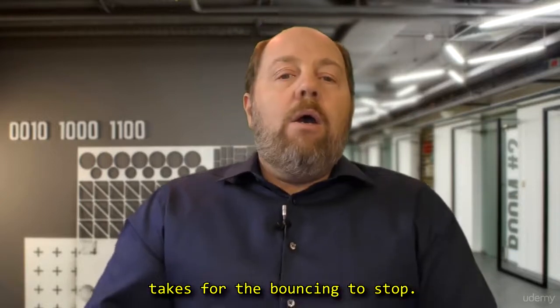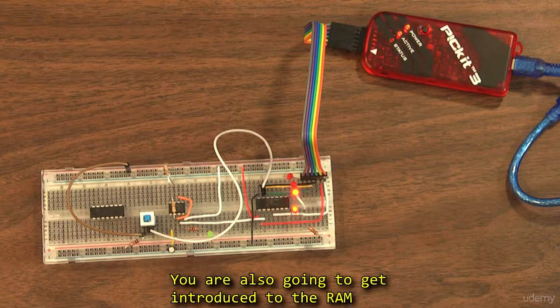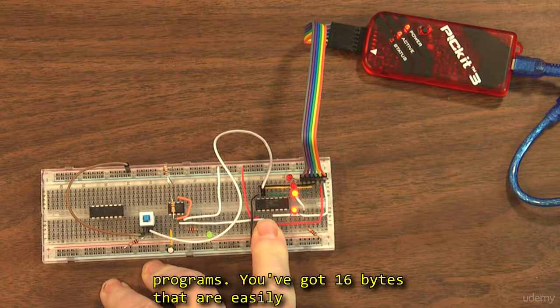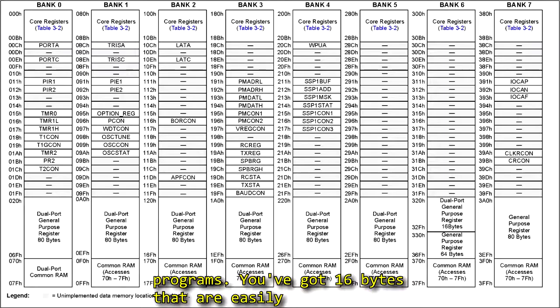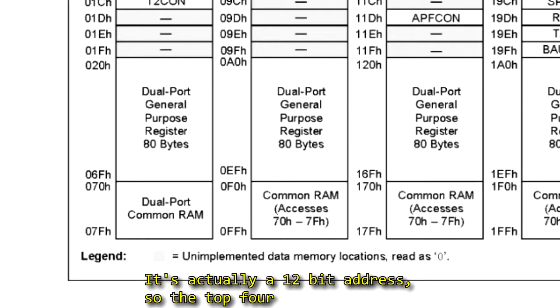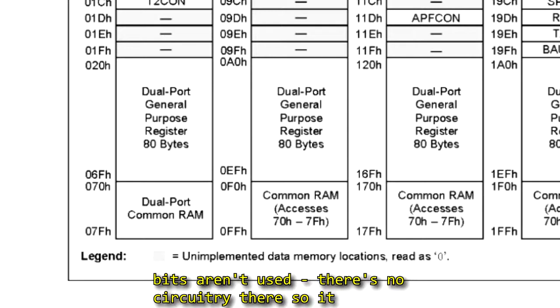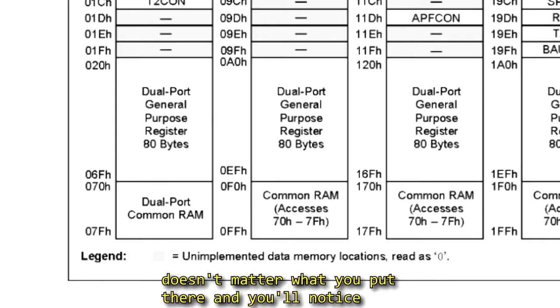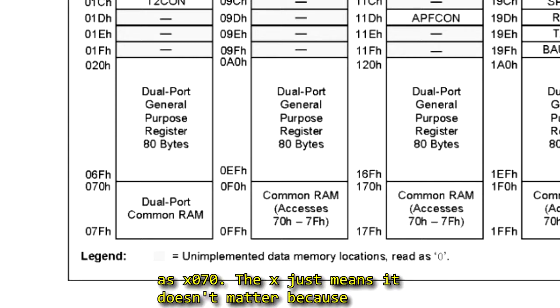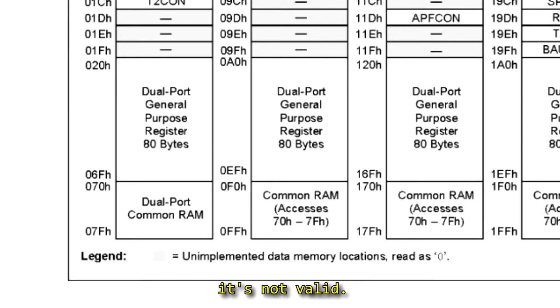You're also going to get introduced to the RAM inside the processor that you can use for your programs. You've got 16 bytes that are easily accessible, and they are located at memory address hex 0070. Now it's actually a 12-bit address, so the top 4 bits aren't used. There's no circuitry there, so it doesn't matter what you put there. And you'll notice in the data sheet where they write the address sometimes as X070. The X just means it doesn't matter because it's not valid.